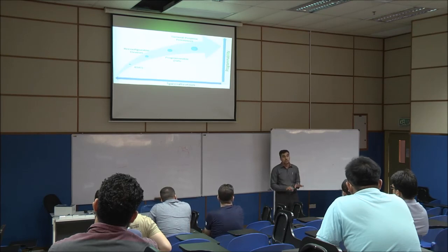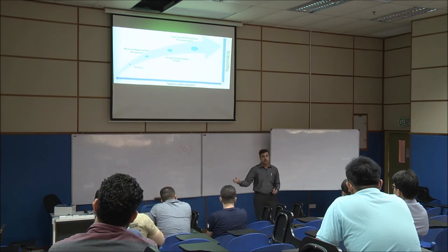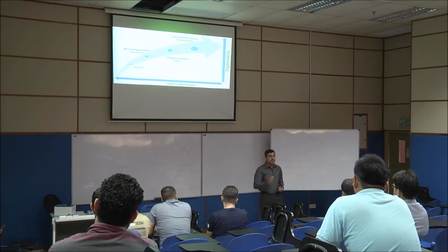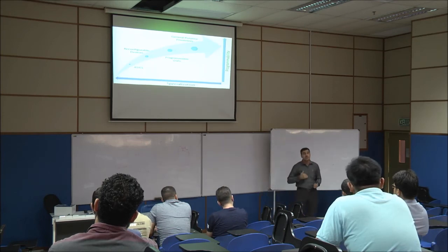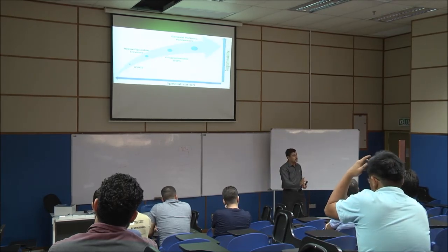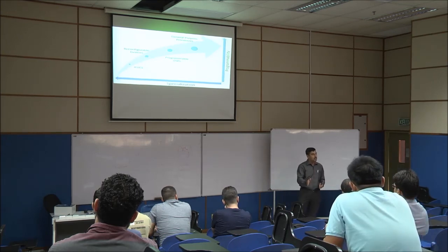For example, you do your development by using FPGA. After you finish, finalize your project, already optimum, with no add-on features, you send your design to an ASIC factory. They make your design as a chip, and your chip will be sold as a chip with fixed architecture. So that means after we finish everything, we send our design to the ASIC company, Silicon Valley and so on. They do what? They make the chip for you. You can sell this chip as a fixed architecture. Clear? So the last stage after development is ASIC.